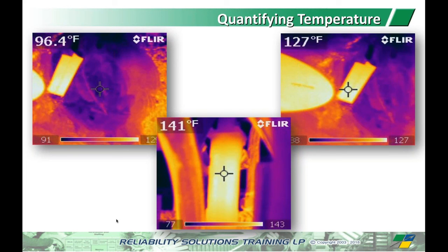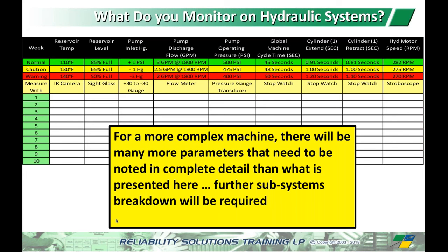The other advantage of infrared is in some respects it's a standoff weapon, isn't it? Because increasingly we're putting cages and perimeter guarding around our equipment, which makes it increasingly difficult to get in there and physically touch the machine or do a conventional vibration route, so sometimes we don't do the proper amount of condition monitoring. Whereas with infrared, I can be some distance away and still capture the heat.